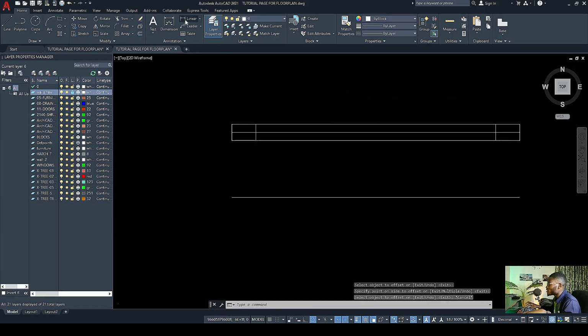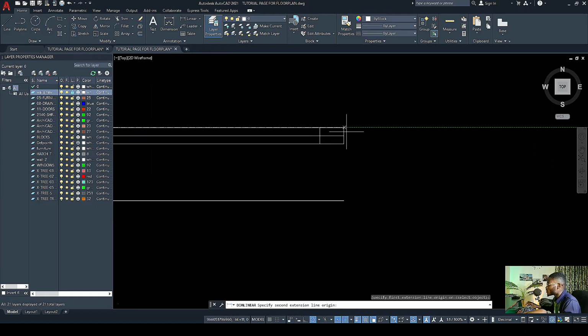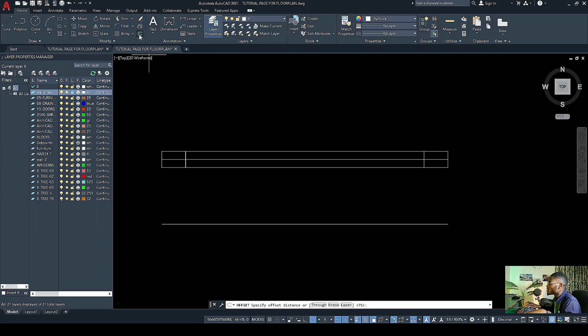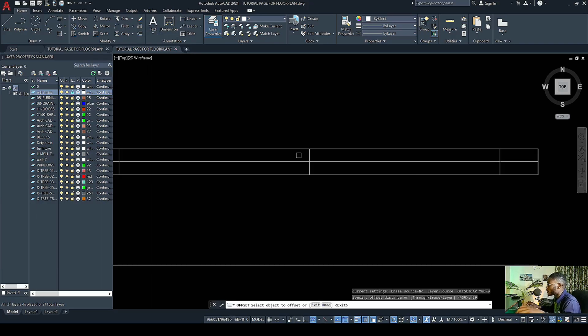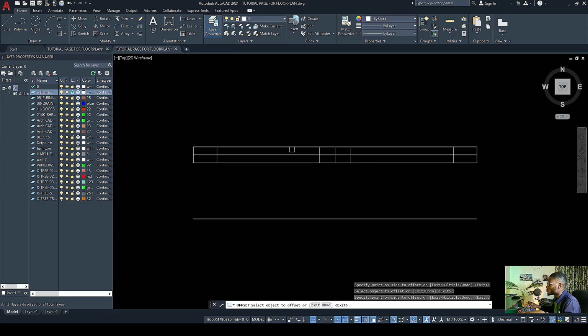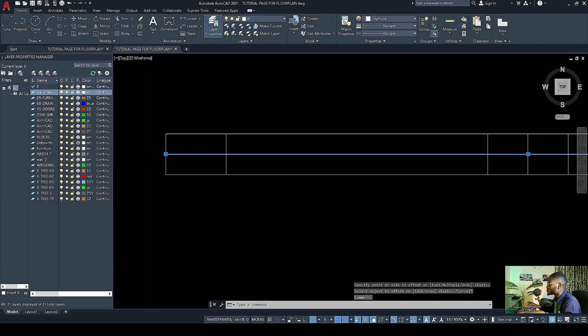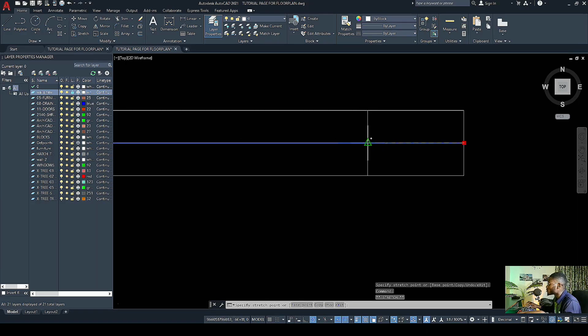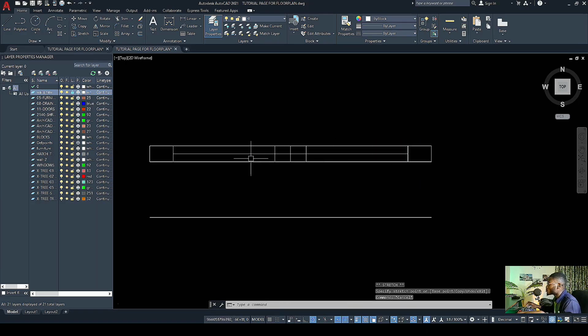So we have this. Let's check the width of our window. The width of our window is what? 900 mm. So half of it will be what? 450 mm. So we'll offset 450. Then we'll move further into offsetting 50. We do this 50 in this direction to our west axis and to our east polar region. So we have this. What are we to do next? We should shrink this inward. Make sure you follow closely so that you won't get lost. You shrink this inward.